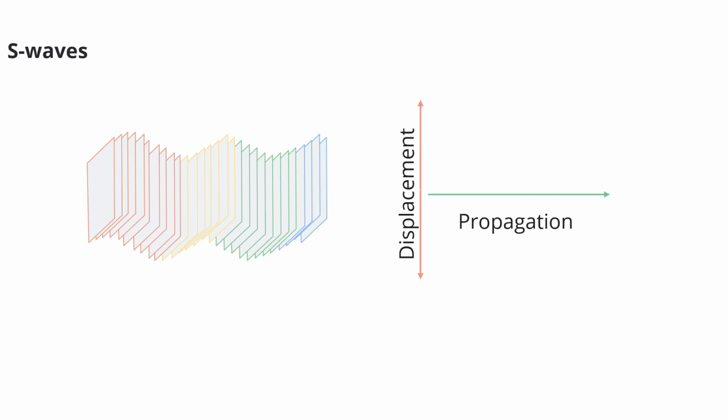As molecules of the rock are deformed, shear energy causes them to vibrate in a direction perpendicular to the direction of energy propagation. Shear energy traveling through the formation is re-radiated into the borehole, and the resulting fluid pressure wave is then detected at a receiver.